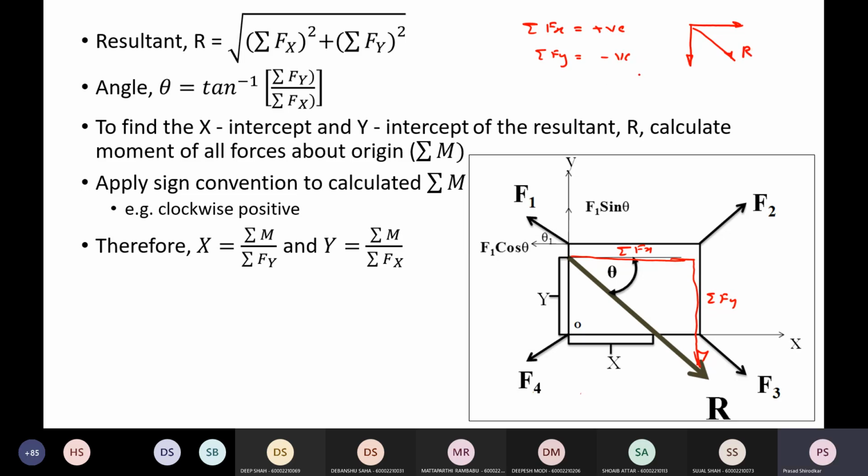This will be the direction result. Okay. And I calculate the moment about the origin, summation M about origin, and I get that, assuming clockwise positive, as a positive value. Correct. So I have to place this force R along this direction, and it should create a clockwise moment effect on the origin. It should turn this plane in this clockwise direction.